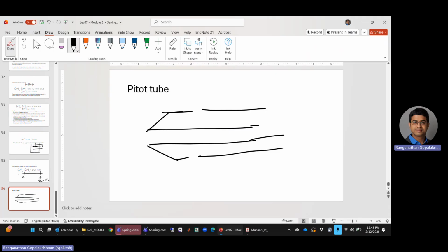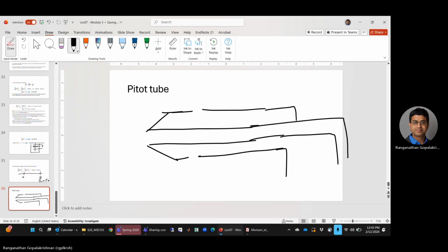These two tubes are disconnected. A pitot tube that is mounted outside the aircraft is going to read the total pressure, the dynamic pressure as well as the static pressure, and I'll tell you how. The pitot tube that is installed inside your aircraft is just reading the cabin pressure.